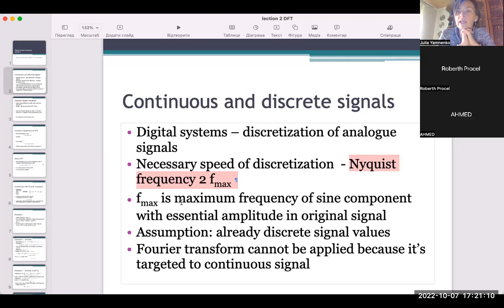As Robert today asked me about phi, phi is a phase shift, and the graph that you should construct in your first practical work is the dependence of module and this phase shift on the frequency. And for different frequencies, we will obtain different values of the module and phase shift of the signal. And these values of the Fourier spectrum at different frequencies are called harmonics.